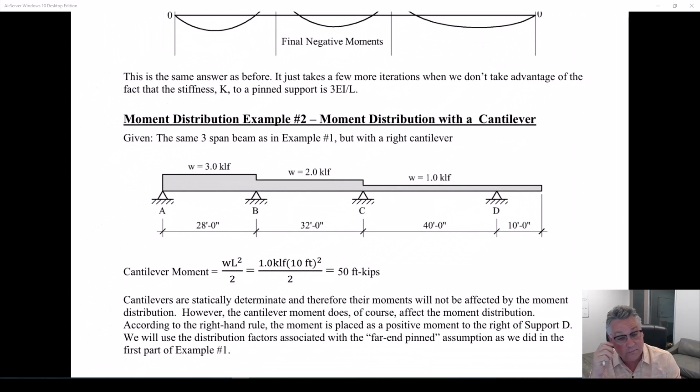I put cantilevers on a lot of times. I love cantilevers. The post-tension concrete loves cantilevers. Cast-in-place concrete loves cantilevers. Steel has to weld a lot to create a cantilever. Wood has to basically frame over a post. So at one level you can do a cantilever on wood, but if you're doing a 3, 4, 5-story building, you're allowed to get a 5-story building in wood, cantilevering is not very easy. You really have to jump through some hoops and do some strange framing to build cantilevers into wood. Same in steel. There's a premium and an expense and a complication.